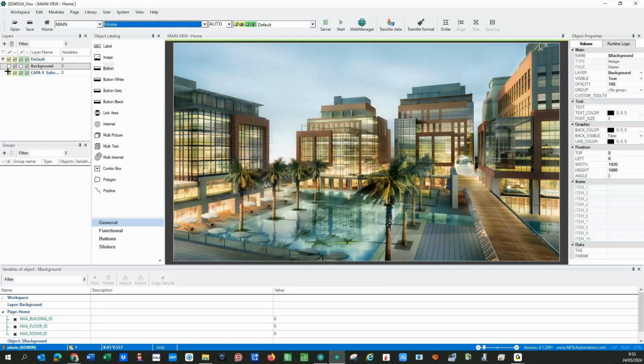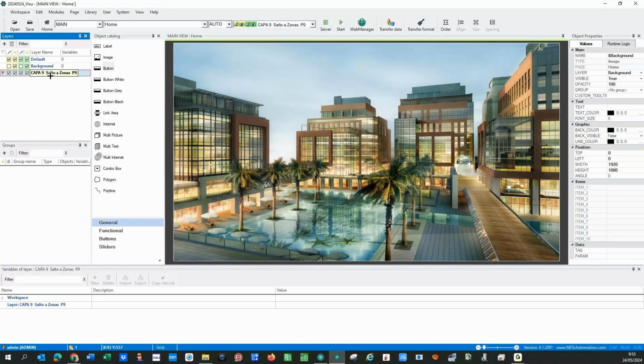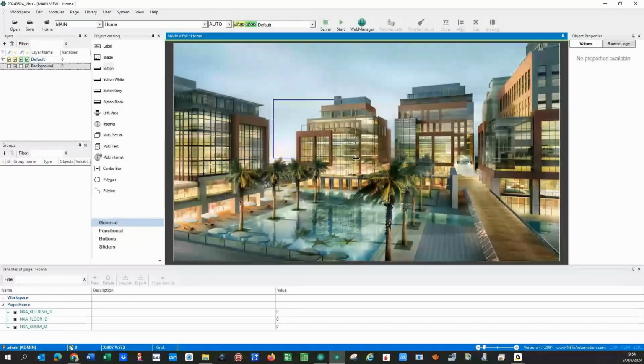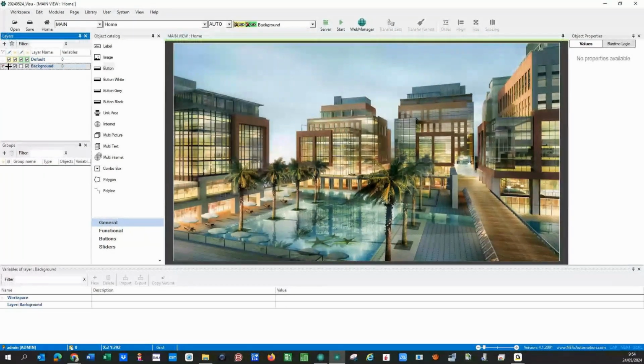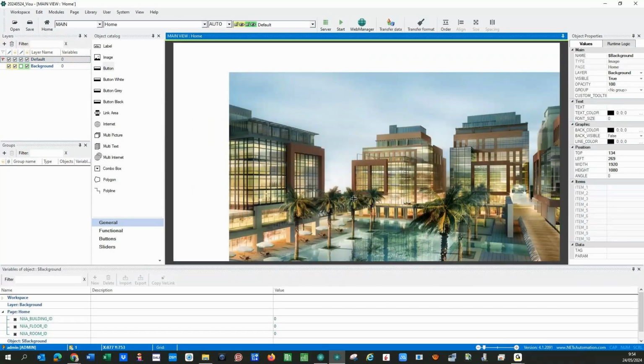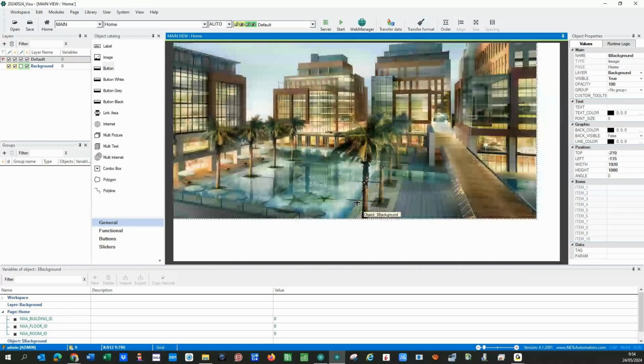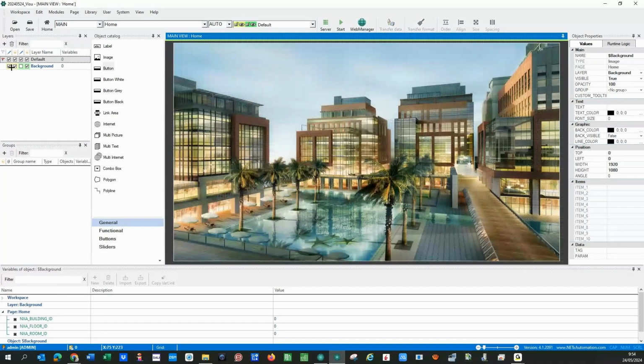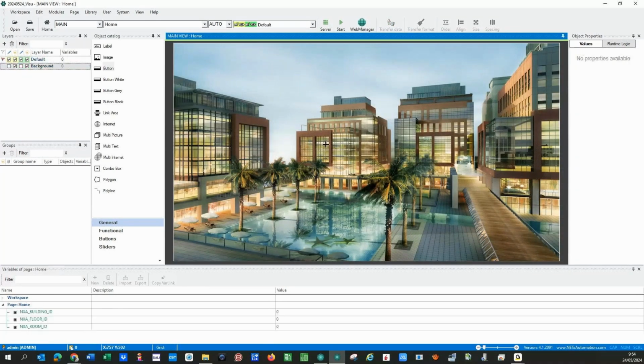Okay, on this layer, maybe I insert some element and it was created, one of the elements I created or whatever, I will delete it. So this is my layer, but this background, I cannot move this element because the background has no edition permissions. If I select this tick, then I can move it, as you can see, because now it's editable. If I unselect this tick, it's not possible.